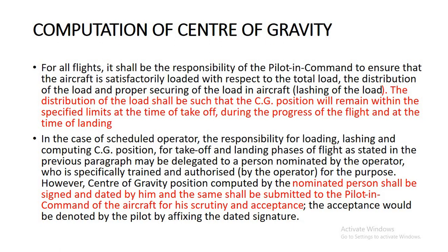The distribution of the load shall be such that the CG position will remain within the specified limits at the time of takeoff, during the cruise flight, and at the time of landing. This should be ensured. The same thing I said earlier: in the case of a scheduled operator, the responsibility for loading, lashing, and computing, lashing means tying and securing, and computing CG position for the takeoff and landing phases of flight as stated in the previous paragraph may be delegated to a person nominated by the operator who is specifically trained and authorized for the purpose.